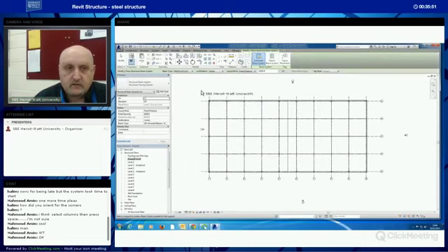I won't save it. For the beam system, if you select or mouse over the beam in this direction, you'll see that it's wanting to place the beams vertically. If I mouse over a horizontal one here, you'll see it wants to place the beams horizontally. And I can change the beam type in here. I'll do a few. That's horizontal, and it's usual for sensible reasons to alternate.